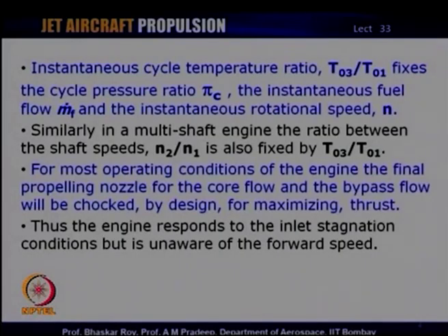The basic operating condition of the engine: we have the propelling nozzle for the main core flow or the hot flow, and we have another nozzle for the bypass flow, which is the cold flow. Typically, it is assumed that for most of the time of operation of the engine, this is choked, and this is by design. The purpose of doing this by design is to keep the thrust as high as possible for every operating condition.